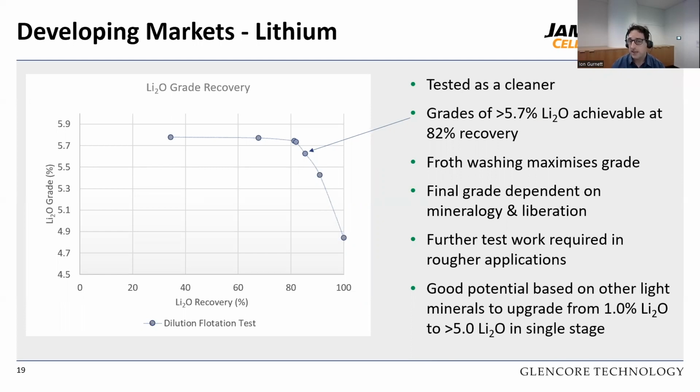Key things here to make notes of: with the froth washing will maximize your grade, i.e. get rid of all that entrainment. Your final grade is very dependent on mineralogy, as you'd expect. And there was very good potential based on other light minerals to upgrade the lithium from about 1% to greater than 5 in a single stage. This site was interested in some of our work, and there is further test work required in rougher applications, but what I really wanted to identify is some of the potential that this technology can do for you in these applications.